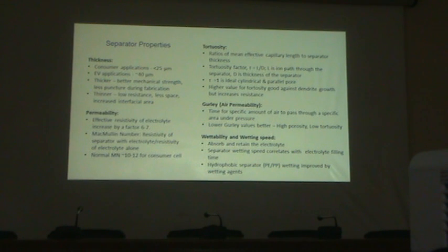By the way, there are one of the few hydrophobic things that stand inside the battery. One of them is a separator. Graphite is the other one. But the other side, cathode, is our problem side, which is hydrophilic, just for information, right? Because even LFP that we work with is quite hygroscopic. If you check the literature, there are results in which water is absorbed if you just leave LFP in the atmosphere for a long time.